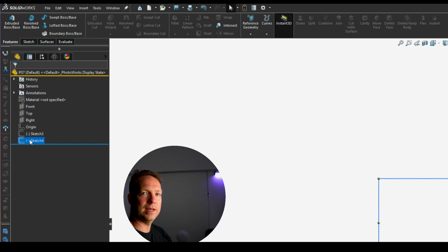And that's a very easy way to go through your files later, once we've started building out multiple features, to make sure everything in your file is fully defined, because you can see it in its sketches. There are very few rare examples where sketches will always be underdefined. One of those examples is using text tools. All right, we'll highlight that later in the course. It's not imperative for every single sketch to be fully defined, but any that are using geometry to create your parts, you want that to be fully defined.